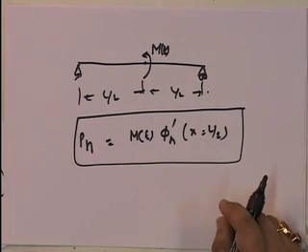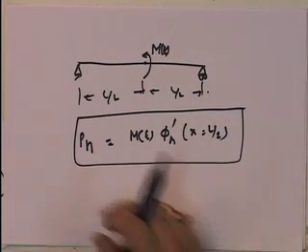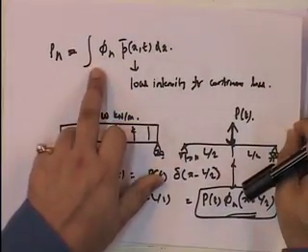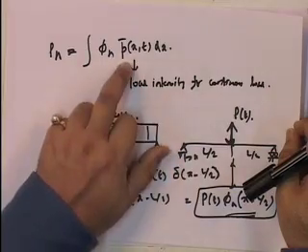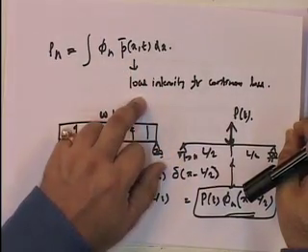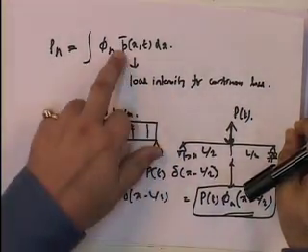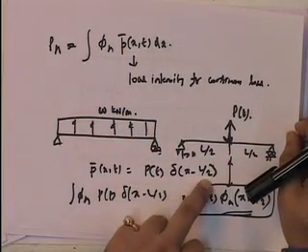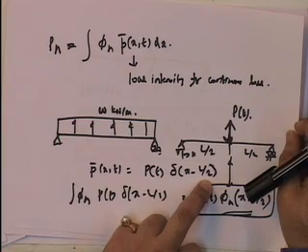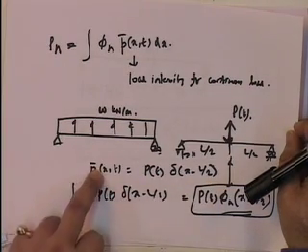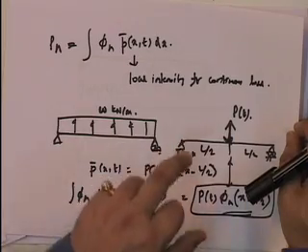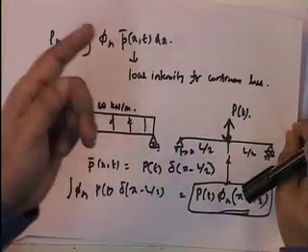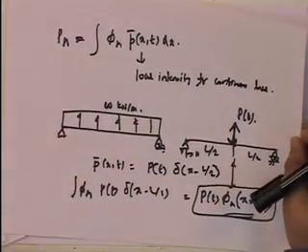So, you understand the point? The point that I am trying to make is that P bar phi n is essentially for load intensity for continuous load. So, this defines the load intensity, and of course, if you have a continuous load, you can always define it in this fashion. And the other way to do it, if it is m of t, it would be phi n prime at x minus L over 2, which is the slope at a particular point.